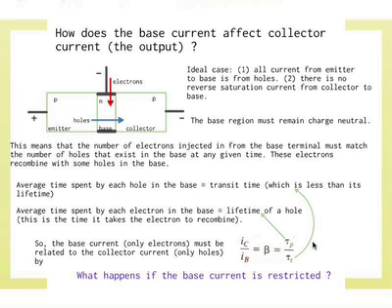So if I restrict the base current, my whole injection has to go down in order to maintain charge neutrality in the base. You see that? In other words, if I treat emitter, collector, base, and I'm only looking at the base, if I send in a small signal to the base, when the signal is less, it will automatically make sure in terms of charge neutrality that the whole injection will correspondingly be less.